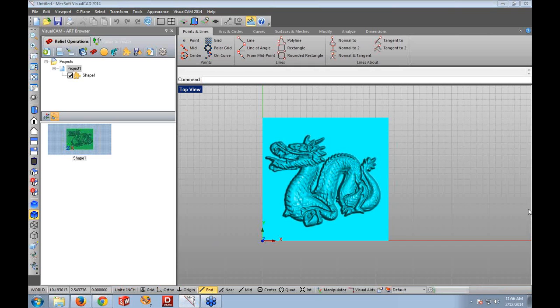Yes, you can machine multiple parts at once. You can create multiple work offsets, or you can bring in multiple different parts. You can import geometries and then program each part. However, there's only going to be one stock that you're defining, but you can define machining regions or areas and define work zeros for each part that you're trying to program.